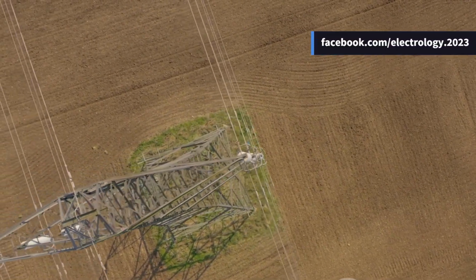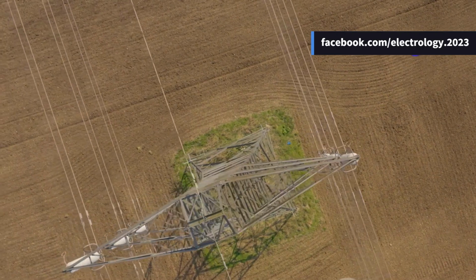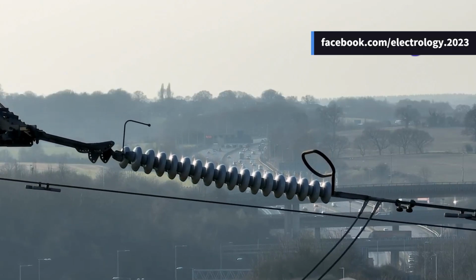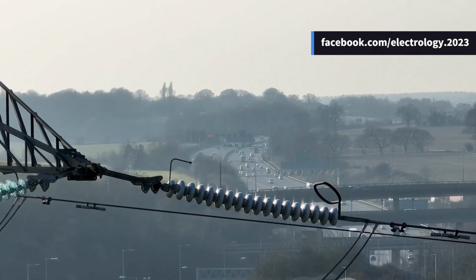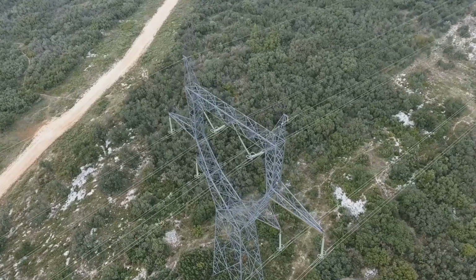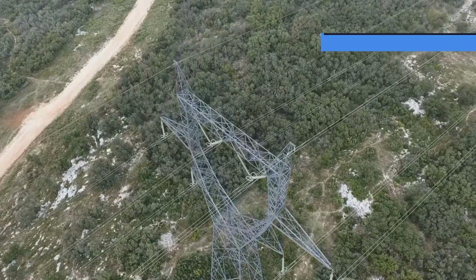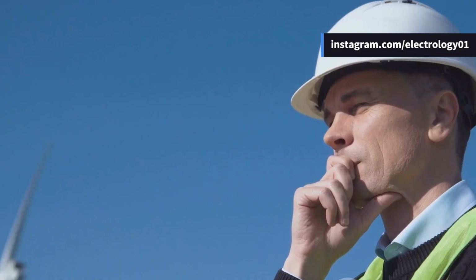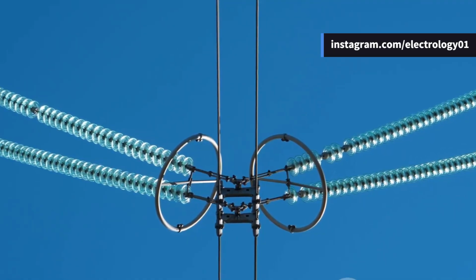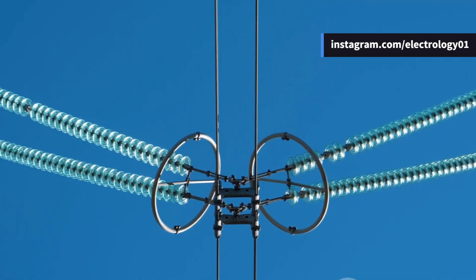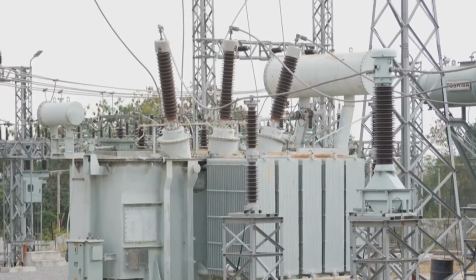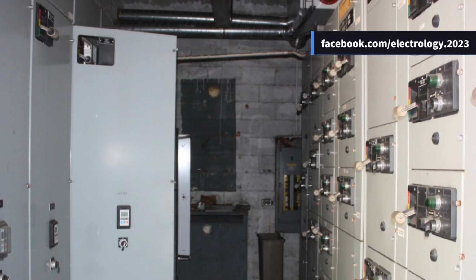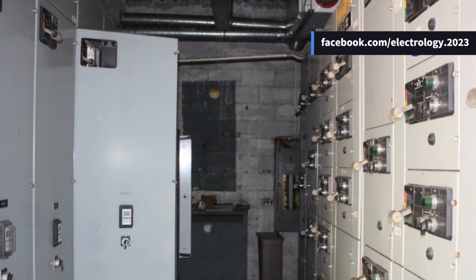We know that when the transmission voltage is increased, the amount of conductor material required gets reduced. That means we can save money on the conductor material. So naturally, it feels like using the highest possible transmission voltage is the best way to reduce costs. But it's not that simple. As transmission voltage increases, the cost of insulating the conductors also rises. On top of that, the cost of transformers, switchgear, and other terminal equipment also starts increasing.